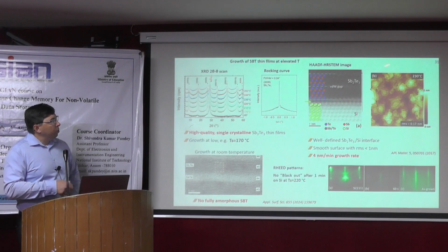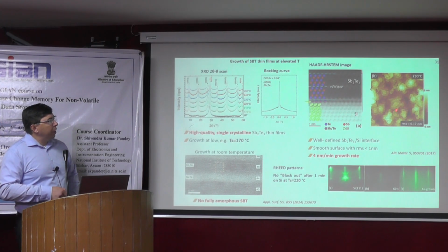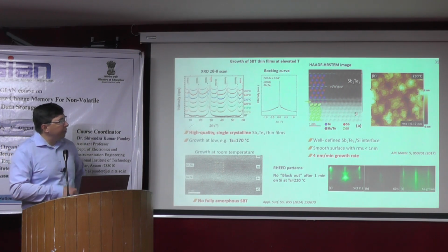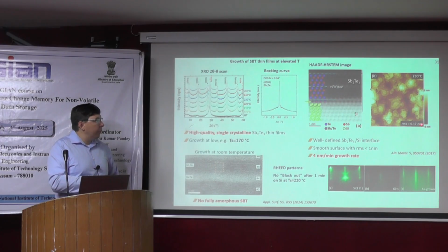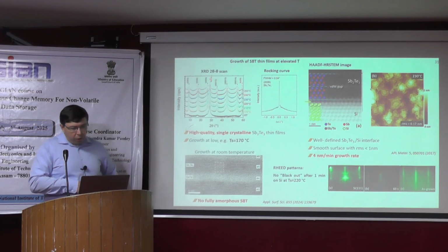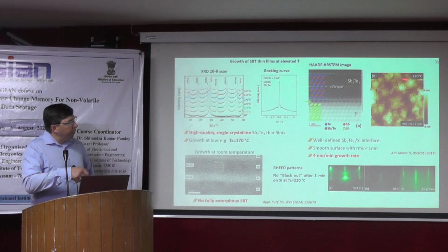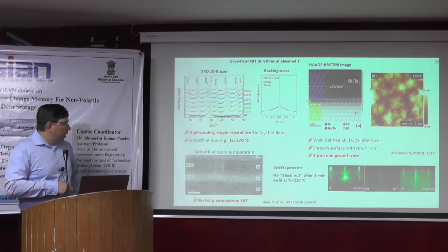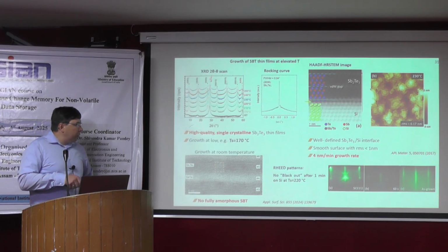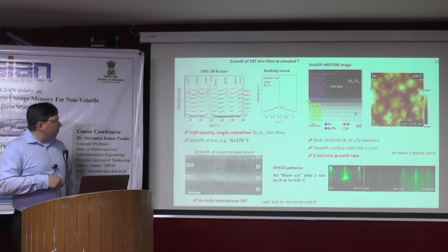And if you do AFM measurements, you see nice domains like here, steps along the thin films. It shows you also very high quality and very, very low roughness, like 0.2 nanometers. And it's also showing you spiral growth of this antimony telluride thin films.